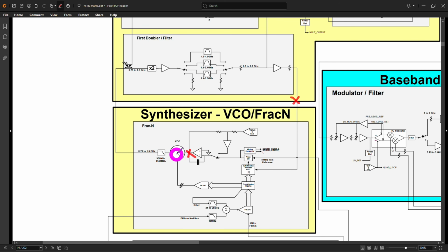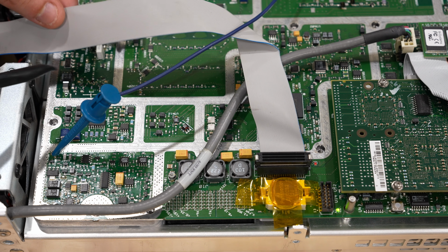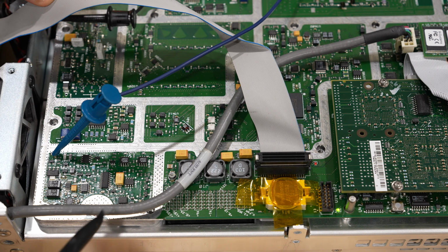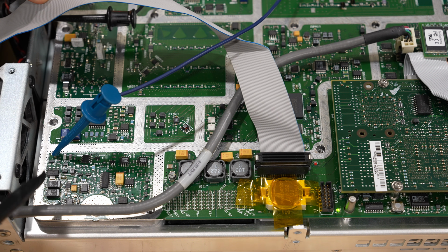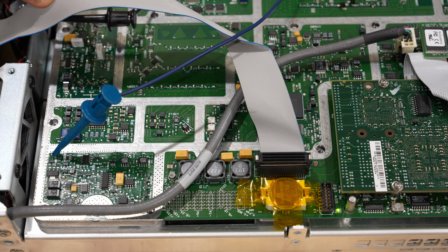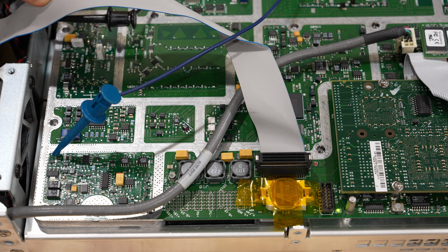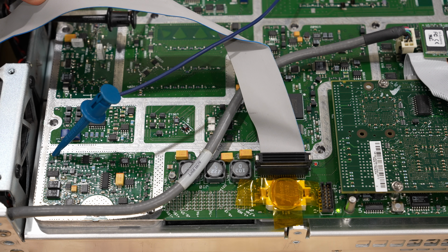So let's try that. And here we are at the bottom. The VCO is over here, and the control circuitry for controlling the voltage on the VCO's varactors is over here. And the tune voltage is actually right there. Nicely, there's a clip there we can attach to. And this voltage is coming from another power supply. I'll show you. This has a tuning range of about a couple of volts to about 15 or 16 volts or so. We can just travel through that range and look at the output of the VCO and see what frequency it is producing.